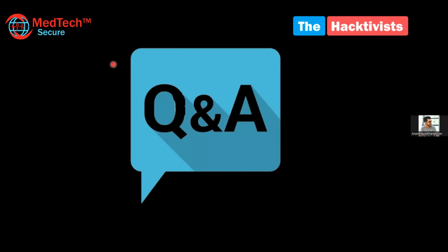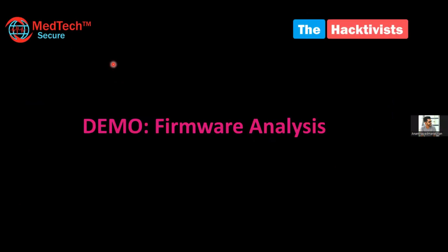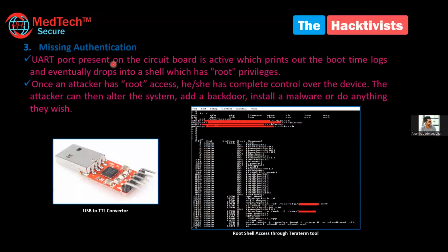Yeah, actually, these are commonly used open source tools. Even what we have looked at today, in the UART part, I think I can show you. Yeah, in this part we discussed the Tera Term tool. This is one of the common tools used for performing this UART test case. With this tool we can find out what data is going through the UART communication protocol. Similarly, for each protocol we'll use a different set of tools.